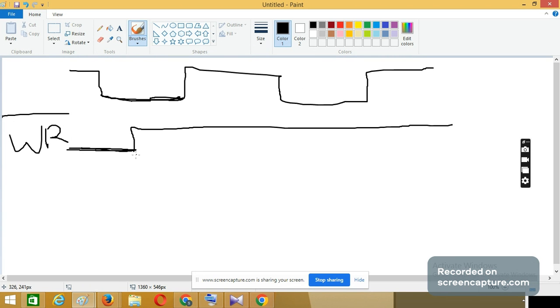So here the start of conversion happens. Whenever WR bar is 0, the start of conversion can happen. Immediately after giving that signal, for the next cycle, it can go to high, and in the next cycle only, it has to go low to start conversion again.